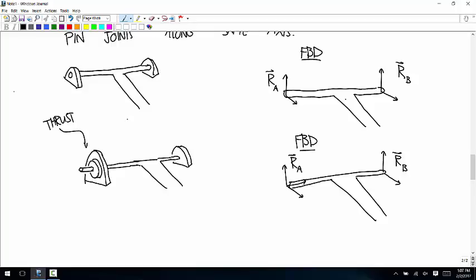there's little flanges on the axis that keep it from sliding through the pin joint. Okay, so in this case, this is still the same as it was in the other one. If it was up to this one, that axis would still be able to slide. But there's thrust provided at the other one by that flange. And so that's what's going on in this.